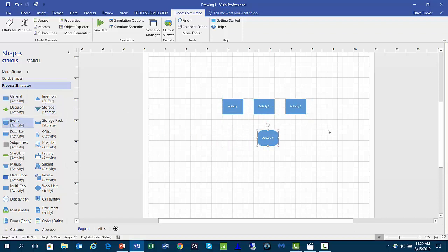Now a third way to get shapes in here is to use the Auto Connect feature. Auto Connect will highlight 4 small blue triangles around the shape that you're hovering over. Then if you slide your mouse over one of those triangles, it will give you several icons to choose from. If you select one of those, it places the shape and it connects it to the previous one.